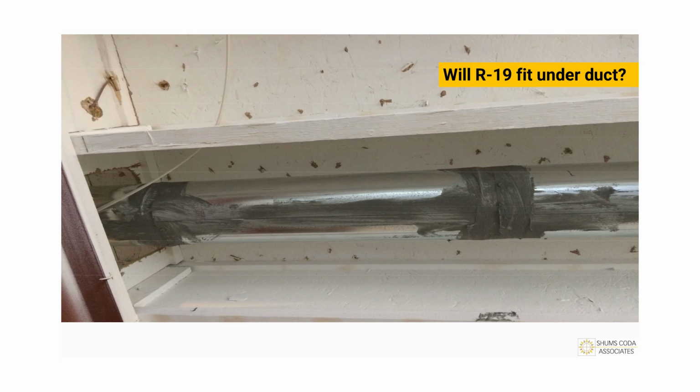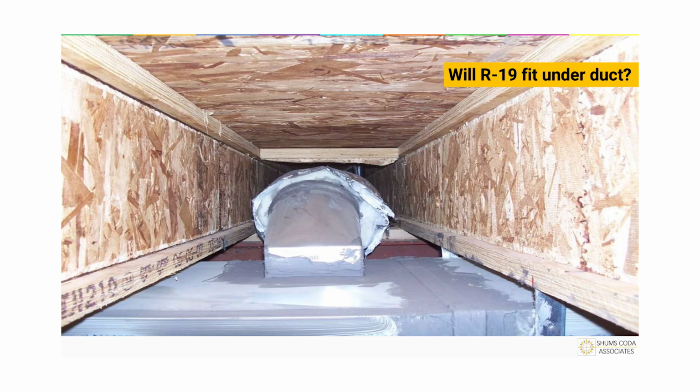So here's the bottom of the ductwork. Here is the bottom of the joist. You can see kind of the distance going on here. All kinds of room. I agree. I think even if you were looking at maybe the worst blown-in insulation, some fiberglass blown-in that's a 2.4, 2.8? Well, maybe not, but you can get quite a bit underneath there, and I think you could very easily get an R19.